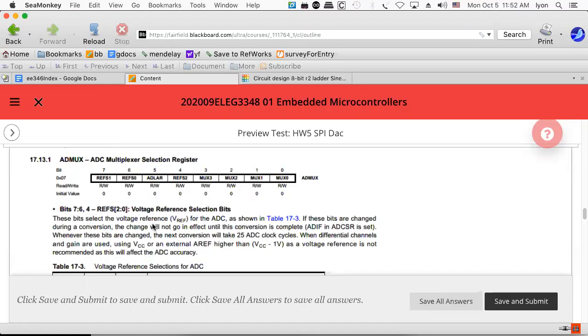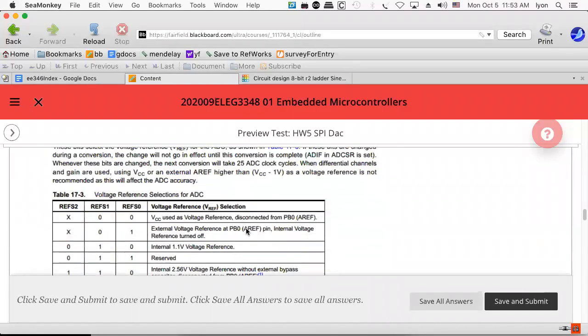If you set it up to an external voltage reference, then you can let the A to D converter float relative to the power supply of the Arduino. That's a real electrical engineering consideration, because guitars don't output 0 to 5 volts. The real world is not 0 to 5 volts. So you have to consider whether you want to use an external voltage reference or the internal voltage reference.